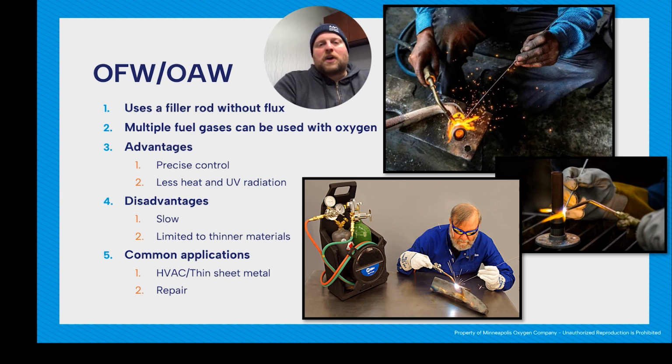Also in soldering and brazing, you're really taking two pieces of metal and then introducing a second, different kind of metal. You are kind of gluing your base metal together. Whereas in welding, you're actually taking your base metal, combining it with filler, and making basically a brand new joint.